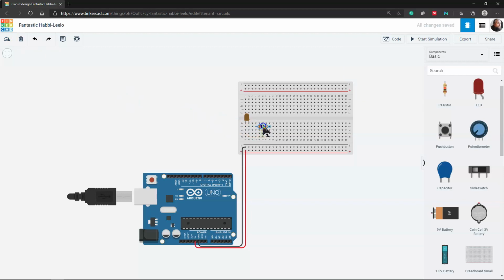And this time, instead of using wires to connect everything, because we have the leads on each side, I'm just going to save space, and I'm just going to have one side of the resistor on the same side as the anode, and another one in a different row that it fits into. Now, this is perfect. Remember, with resistors, it doesn't matter what direction you put it in. It'll still be perfectly fine. It's only for anything that's a diode as far as you're concerned right now.